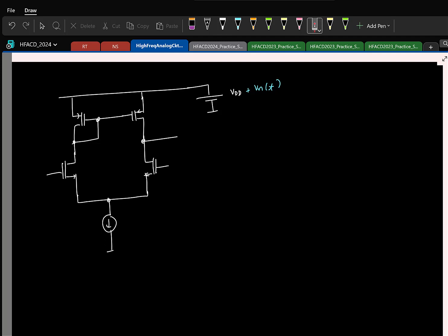So now let's assume that we already put a large capacitor on chip, so the variation in the supply is small. Okay. So if the change in the signal is small, to find how much of this change appears at the output, what can I use? Small signal. I can use small signal because the assumption is this is a small signal. So it's a small signal analysis. You can find the short circuit gm, Rout and find it. That is one way. I'll give that as an exercise for you to do. But this guy is something that we have analyzed extensively. So we should be able to do something better, right?